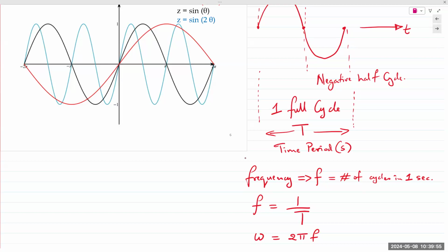So most adapters that we use nowadays will have a rating which says you can use it. It will say input 100-240 volts and 50-60 hertz, meaning you can safely plug that device into any power outlet anywhere in the world. You don't need to do an electric conversion. You might need to do a physical conversion because, again, physical prongs are different throughout the world, but electrical conversion is no longer needed. But again, just to be safe, you should look at the adapters that you are using. So the adapters would state input and output both.